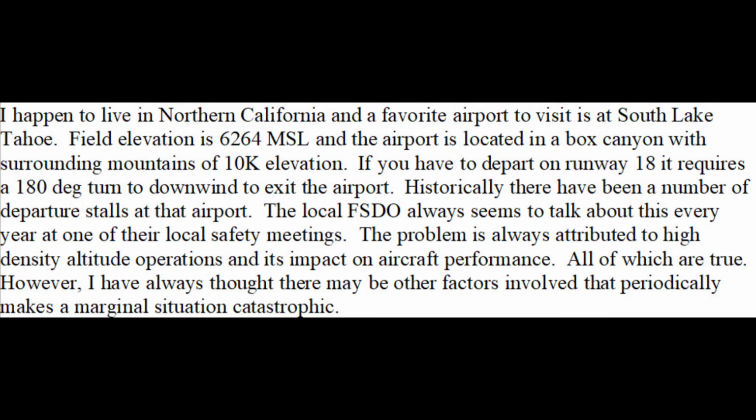I happen to live in Northern California, and a favorite airport to visit is at South Lake Tahoe. Field elevation is 6264 MSL, and the airport is located in a box canyon with surrounding mountains of about 10,000 feet elevation. If you have to depart on runway 18, it requires a 180-degree turn to downwind to exit the airport. Historically, there have been a number of what appear to be departure stalls at that airport.